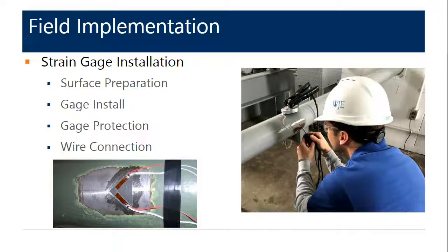Here, the strain gauges are spot welded to the selected drive machinery shaft. Gauges can also be bonded directly to the shaft. However, spot welding is the desired method of adhering gauges to the rotating shaft due to field conditions and durability. The gauges are installed on bare metal that has been sanded to achieve an approximately 125 microinch surface finish.